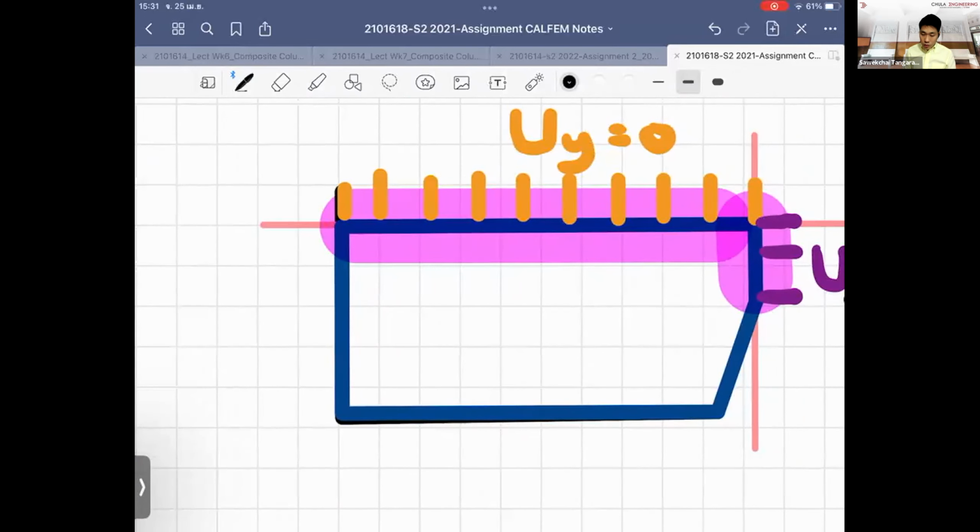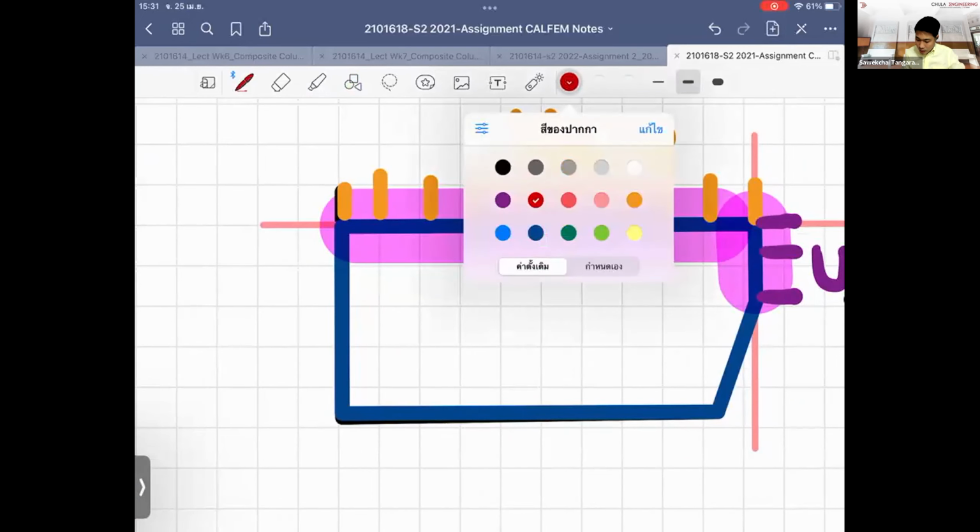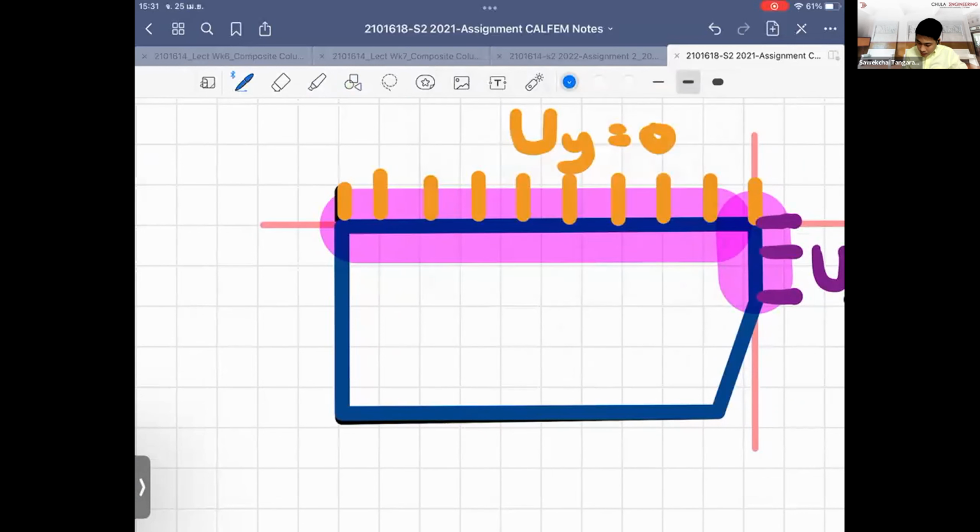And when we want to model these problems, we have an applied force, and the force will depend on how many meshes we want. In the beginning, I want to make it a coarse mesh. The coarse mesh, what it means is this: I want to put the dots, which are the nodes we have here, by just splitting the structure. I try to keep my structure as much like a square as possible.